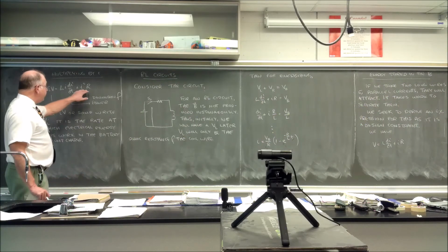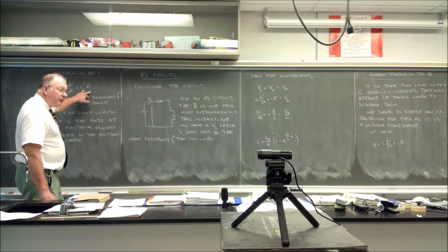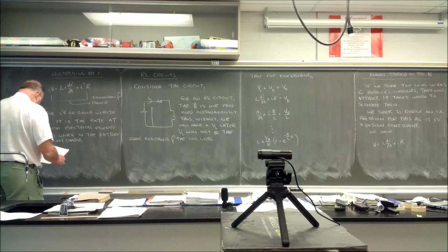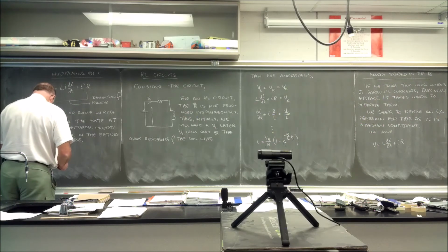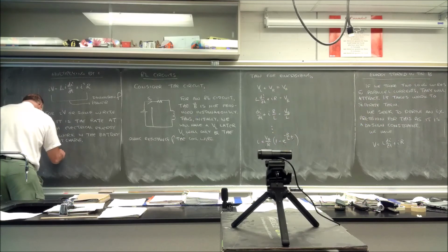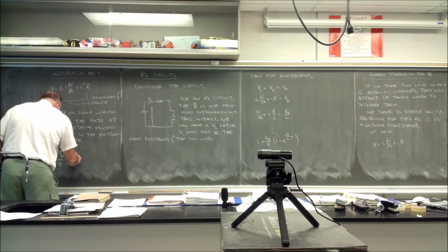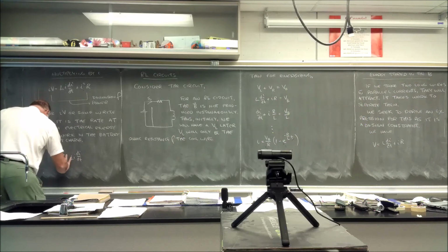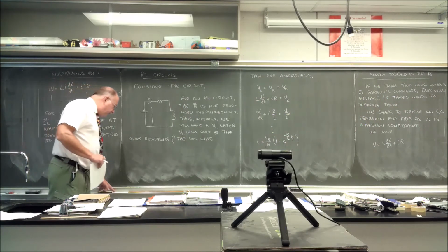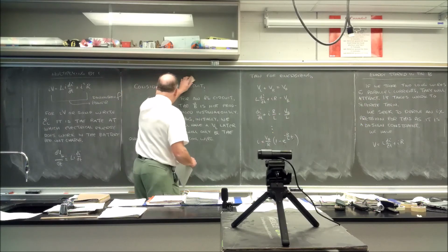We know this is the rate of dissipation of the resistor, so we don't care about that. So then we would say du sub B dt, which is equal to LI di/dt. Of course, instead of B, I'm going to say L, in the sense that the energy in the inductor, because that's what we're interested in here.